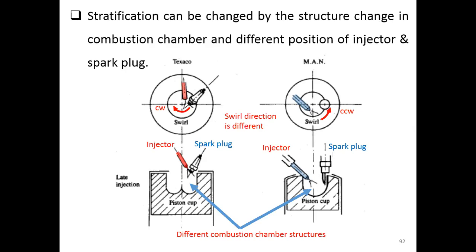So what they said is you can change how the stratification happens by changing the combustion chamber configurations or by placing the injector and the spark plug in different positions. I give you some examples here for these two manufacturers, Texaco and MAN, leading brand names here.